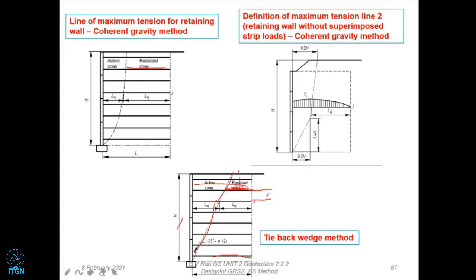So to do that, they made a lot of estimates and found out the maximum stress zone. That means these are all loci of points of maximum stress, like this. This is one point of maximum stress, another point of maximum stress. That's where the failure line is going through. So for that, they assumed that you consider a point at 2H. Okay, draw a line normal at 45 plus φ/2. So at point 2H width actually, you just draw a vertical line. From this point, they assume by and large it's going to be near vertical.